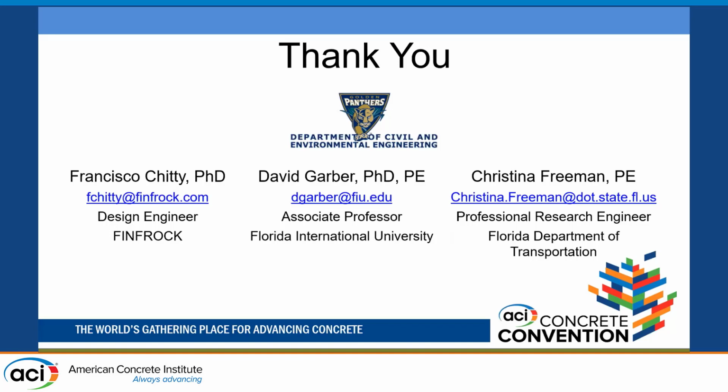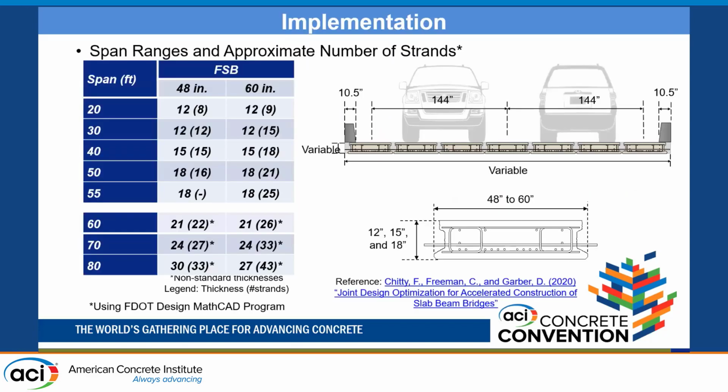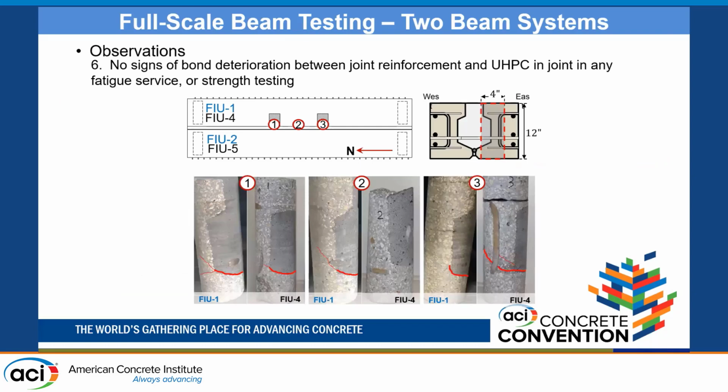I wondered if you had any issues coring, since you were coring against two different kinds of materials. How is it to core UHPC? It was tough. It was very tough, but we were able to core it because it was only 12-inch thickness. I can go back and show you, for example, we broke some cores here. You'll see this one is missing one piece and this one is cracked. That was during the coring. Did they end up with a lot of ribs in them because your coring equipment kept moving? No, not that I'm aware of. It was very smooth.